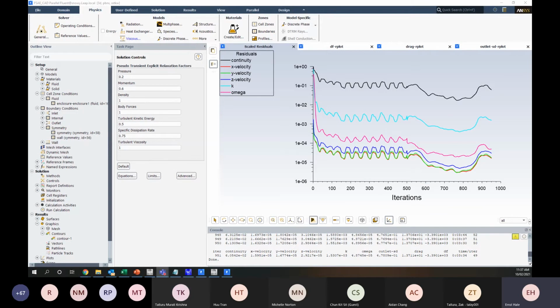But like I said, the validation and the ability to select an appropriate turbulence model is based on prior research. It's based on other people's models that they've built in the past. It's based on models that your research group is using and why, not just an understanding of the theory. Okay, it takes a lot of research before selecting a turbulence model and being sure of that selection.